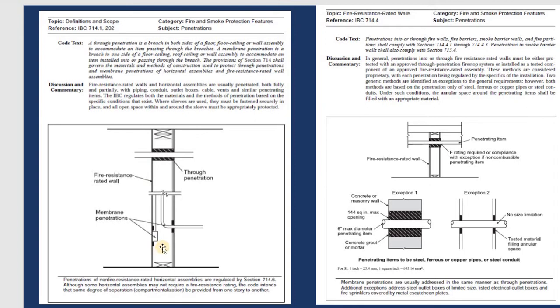This is one section cut from the building. You can see that some of the members of the construction have penetrations, and through the structure, between them you have the ceiling or the soffit, and between them you also have penetrations. If this is a fire resistance rated wall, you need the material on both sides of it to make sure it is qualified for how many hours of fire resistance.